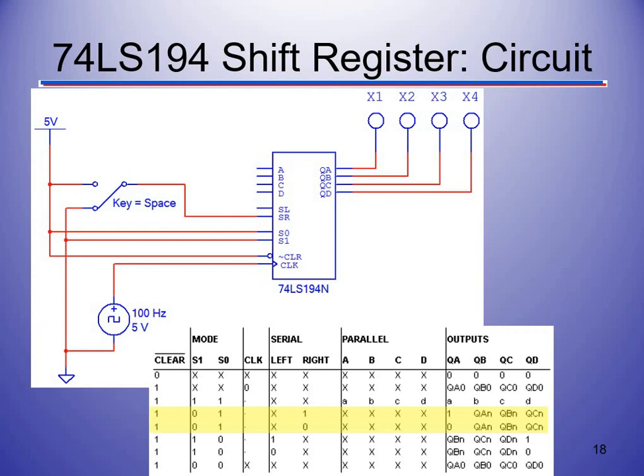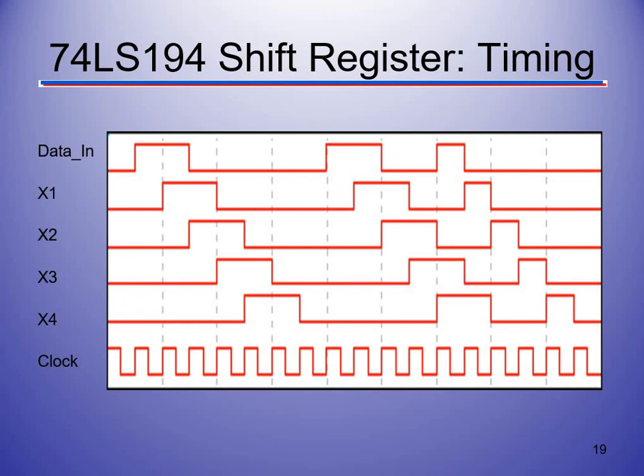And this particular case right here that we're looking at, that's set up for a serial. So we can send in either our 5 volts or our ground. So we're going to send in a 1 or a 0. Our clock is still going to go, as it has been, high, low, high, low, high, low, constantly. But we're going to send in a specific signal. So you're going to do this in a lab using Multisim, and you should be able to understand where the shift register is.